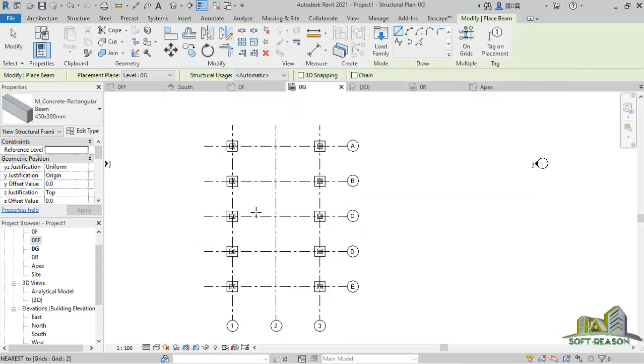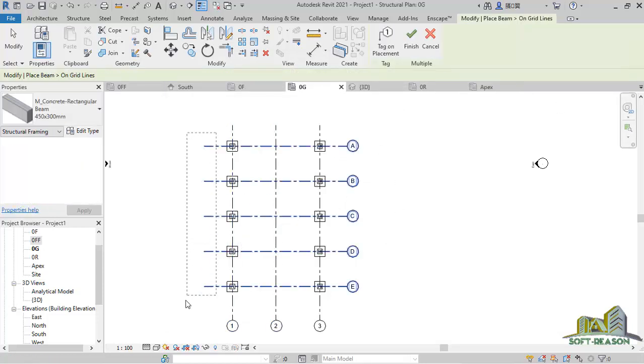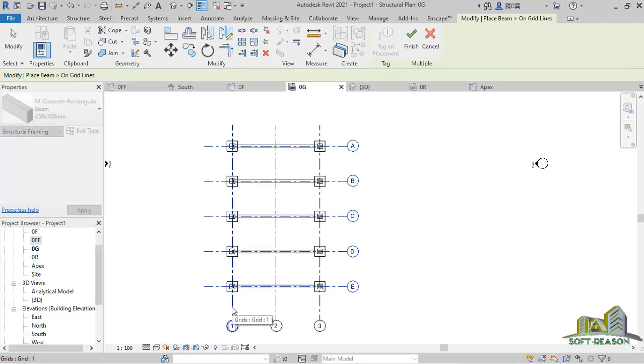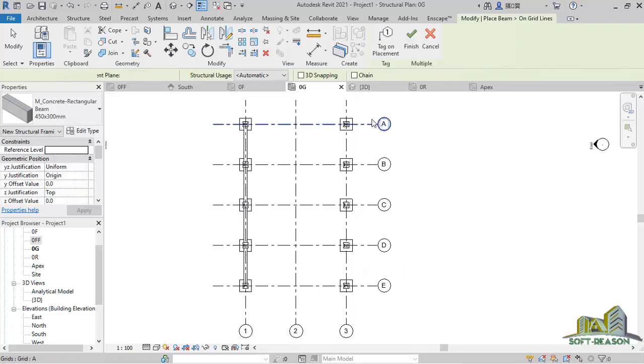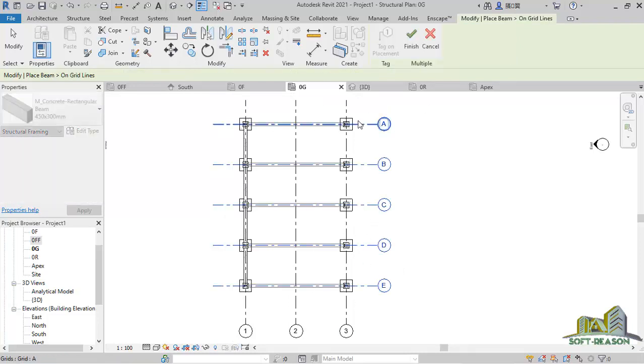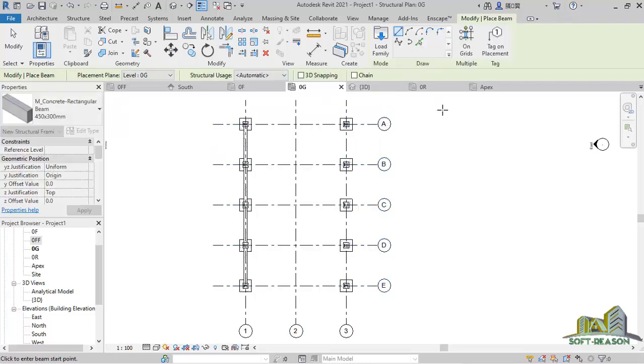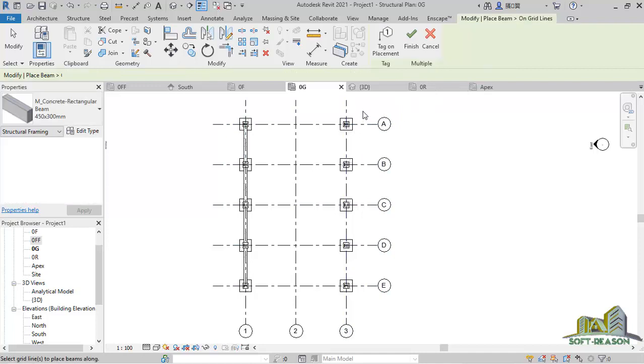We'll be using the same method to add these beams. Alright, so you just click on grids, click on that, select these grid lines, then this particular grid line that intersects them, click on it, it will be instructed. So these are the beams at that level of OG. Alright, you do the same thing, click on finished, and you proceed again, click on grid again. Oh, sorry, it's not intended, you cancel that. Alright, you just have to click on grids, highlight all of these grids, select that one to intersect it along that direction.